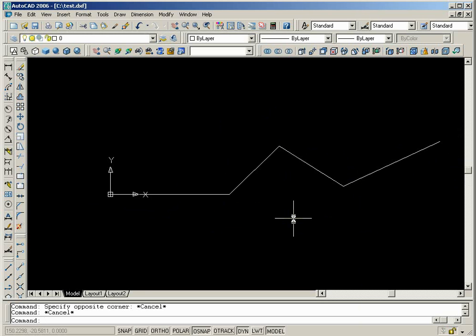And that's sort of the basis of Sidewinder. It lets you bring in a polyline. If you open up a 50 meg file with all kinds of lines and layers and everything in it, Sidewinder doesn't have a clue what you're talking about. You need to have a single file with just a single polyline in it, and you're all set.